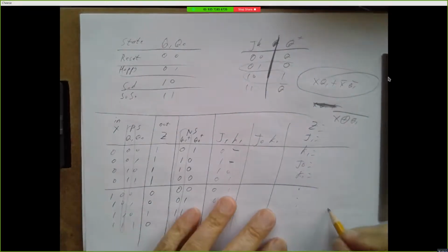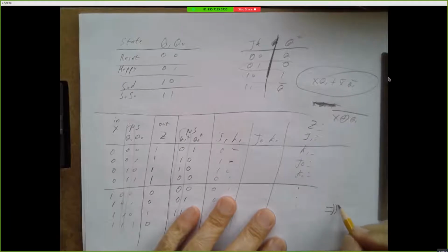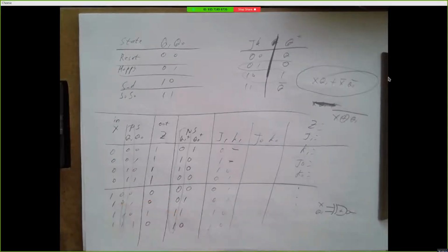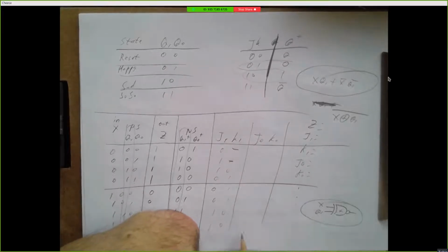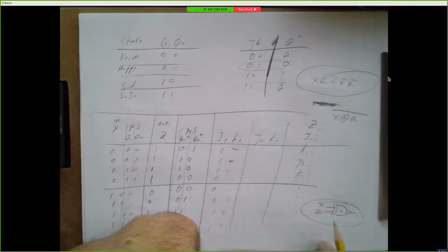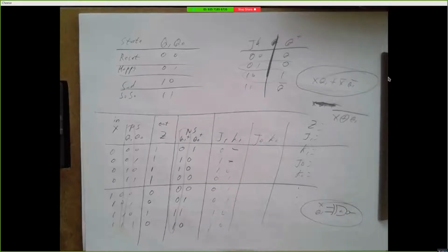And so if you want to build this circuit, you make an XOR gate with an inverter on the end, and X would go into one of the inputs and Q1 would go into the other. And in all of the homework assignments that had this in the circuit, there was no mention of an XOR anywhere in their work. It went directly from a truth table or an expression like this into an exclusive NOR gate. That's a step that you want to show.